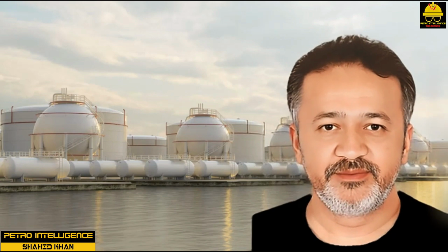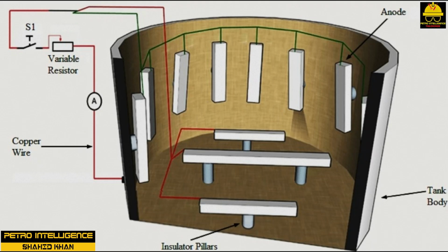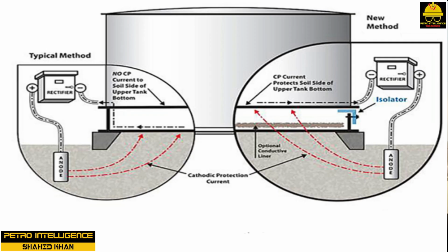Cathodic protection. Electrochemical corrosion control in the chemical processing industry is best taken care of using cathodic protection. Electrochemical corrosion causes tanks and pipes to prematurely corrode and fail. Cathodic protection utilizes a direct current device from an external source to counter the discharge of a metal submerged in a conducting medium. Typical conducting mediums include soil and water. The base of any above-ground storage tank is vulnerable to electrochemical attack and corrosion.